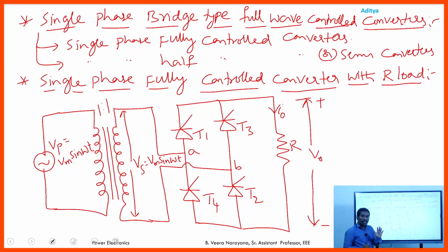Due to the switching of these devices, harmonics are injected into the source side, and other components connected to the same source may be affected. To overcome that problem, we provide the isolation transformer. If harmonics are generated during the switching of SCRs, they circulate in the secondary winding of the transformer. Hence, to prevent the harmonics from being injected into the source side, we provide the isolation transformer.